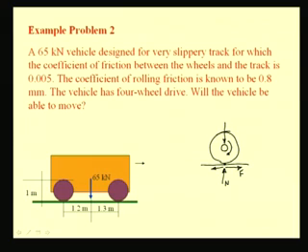So, how large could this thrust be? It could be maximally equal to the limiting value of friction at this point, because beyond this, the point will tend to slip. If this point does not slip, then the axle will experience a forward force and thus the vehicle will propel. So, the forward motion of the vehicle depends on the developed thrust force being less than the maximum available friction,